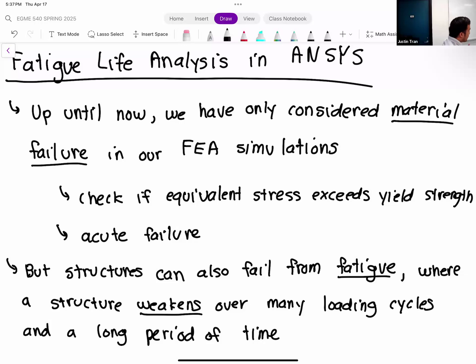So the way that we kind of perceive it happening is that the material or the structure gets tired. Right? So just like humans, after we do things repeatedly for a long period of time, we stress ourselves. We get fatigued, we get tired, right? And so we can't handle things like we could when we're full of energy. And so when a material gets fatigued, its threshold for failure kind of goes down. And so a smaller amount of load, which normally would not cause failure if this part or structure were brand new, under fatigue could cause failure of the structure.